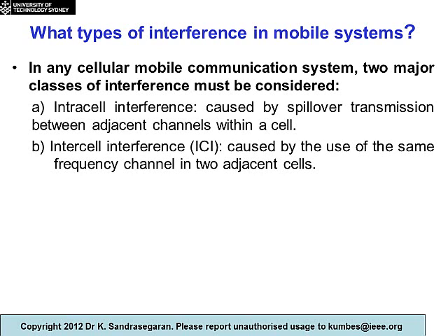Because each UE is transmitting on a resource block, and the OFDMA symbols are orthogonal, there shouldn't be any interference. But however well you design your radio equipment, some amount of transmission could leak over into an adjacent channel and cause interference. That results in intracell interference.